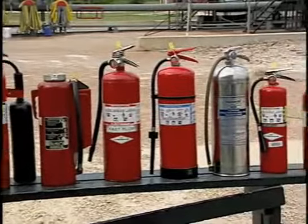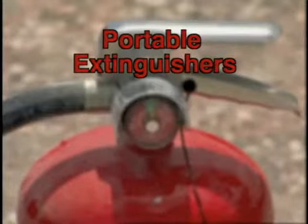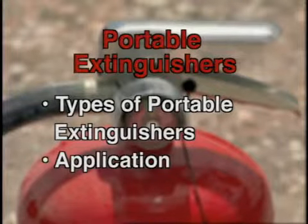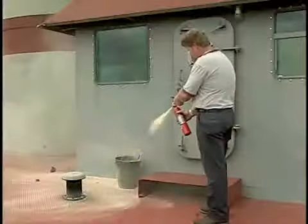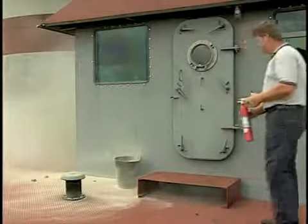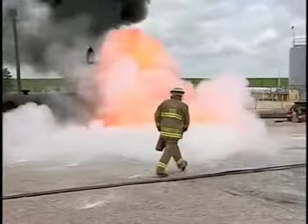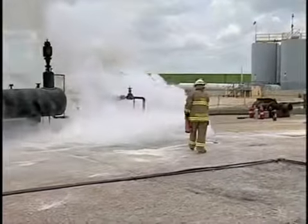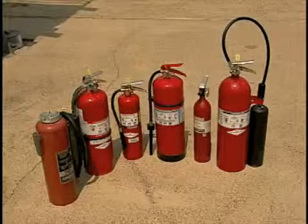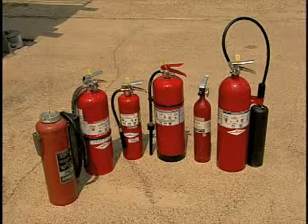The type of extinguishing agent needed depends on the type of fuel burning. In this program, we're going to look at various types of portable extinguishers, their application, and most importantly, proper technique. Technique is so important because the average portable extinguisher has a relatively short discharge time. Larger extinguishers deliver a larger flow rate, so you have more extinguishing agent, but not much more duration. Before we explain proper handling techniques, let's first look at the various types of extinguishers and their applications.